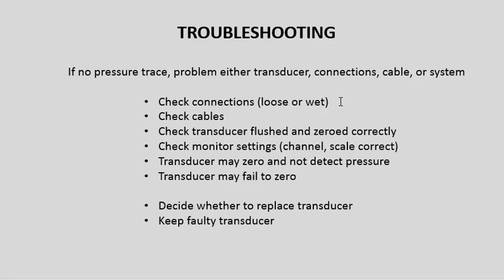Always check the connections. You know, a loose or wet connection simply doesn't work. Check the cables. Amazing how many trolleys run over cables and break them. Check the transducer is flushed and zeroed correctly. You will be taught all this in your prac classes. Check the monitor settings. You may be on the wrong channel, and check that the scales are correct.